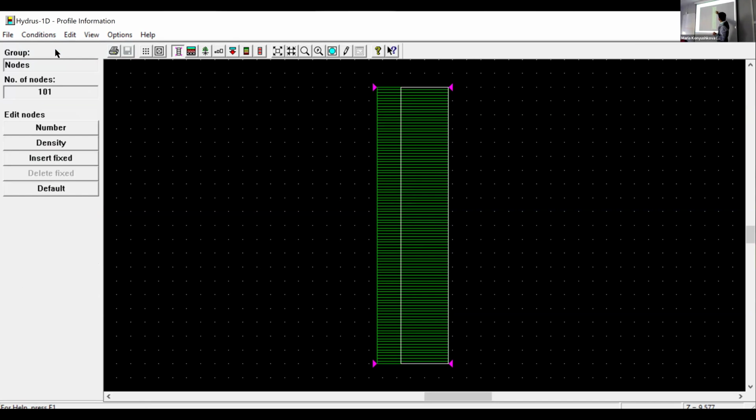If you make it denser here, it is more important because it faces the upper boundary condition. Or if you make it denser here, which means you have a groundwater level and fluctuation, you want to focus on that part. But at the moment, I just put it as a normal one.